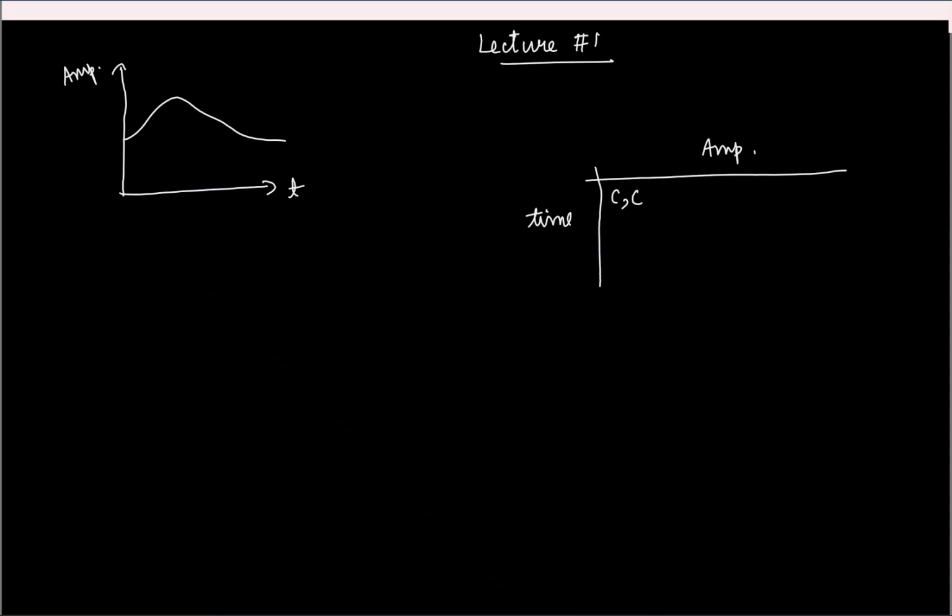So what do you do? Basically you try to save its information at discrete time instances, say like this. And usually we make sure these time periods are uniformly spaced, which means you don't need to save the timing information separately, because the moment I know the rate at which I have strobed the signal, I simply know the time instances also. Similarly, on the y-axis, instead of saving all possible amplitudes, I'll take a range of amplitudes. I'll say any amplitude within this range, I'll round it off to some other amplitude within here, say here. I'll do it for all amplitude ranges. Then I'll end up with a finite number of amplitude levels to store, and these I can encode using binary bits. This is what gives you discrete time, discrete amplitude signals, which is the digital signal, as you know.